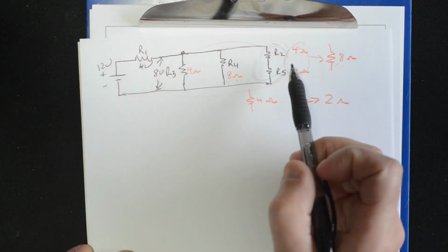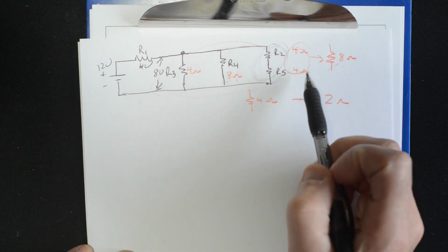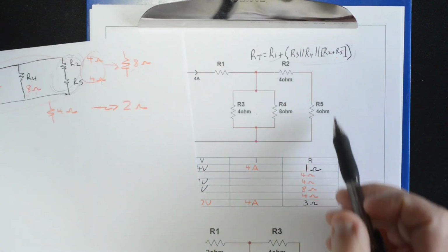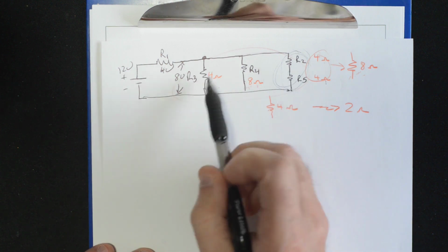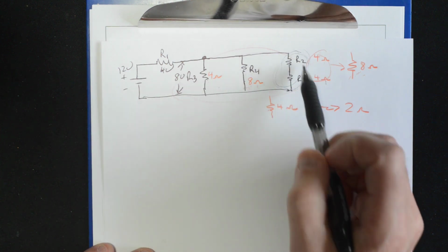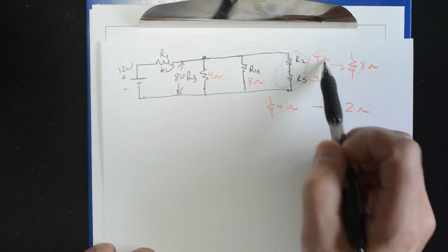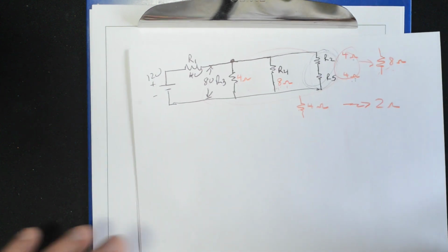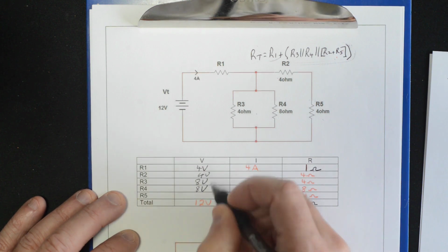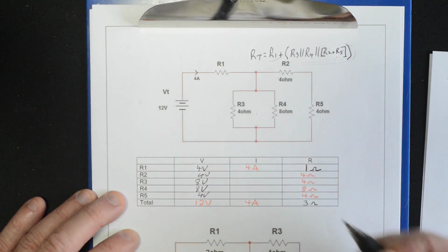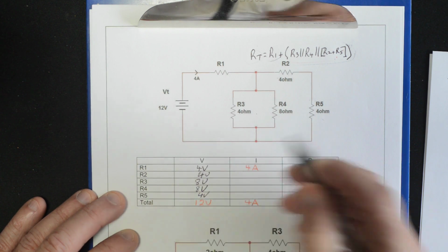And now, there's a couple different ways you can go here. Recognize these are both 4 ohms, a very contrived, nice circuit, which means that if this is 8 volts, this is 8 volts, I have 8 volts across these two total. They sum, but they're the same resistance. So they're simply going to split that 8 volts in half. So you know they're going to be 4 volts and 4 volts. It has to be that way.